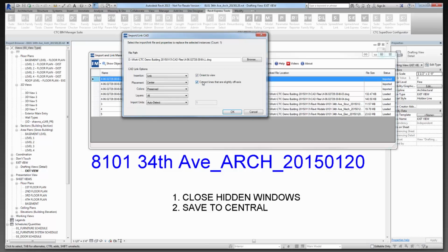So if I had a civil model, by the way, linked in, hopefully it wasn't a current view only, but if I have a civil drawing linked in from my Civil 3D team, and I wanted to create a terrain off of that, if I imported it or linked it incorrectly the first time, I can correct all these things after the fact, which is nice.